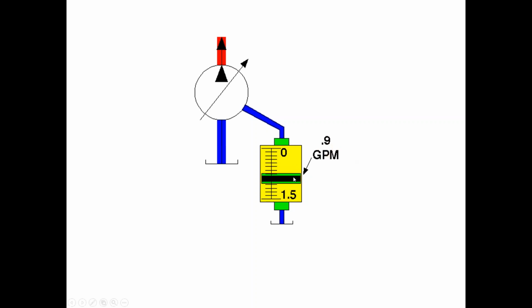As the pump wears, we get more and more. And in general, and it's not hard and fast, but for most pumps, if this figure ever gets to 10% of the pump flow, or for a 30-gallon a minute pump, that'd be 3 gallons a minute, then it's probably getting time to replace that pump. Okay? So tracking the condition of that pump is a real good idea. That way we're not surprised when a pump fails.